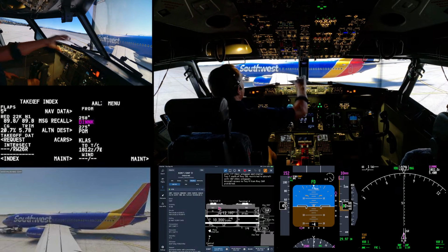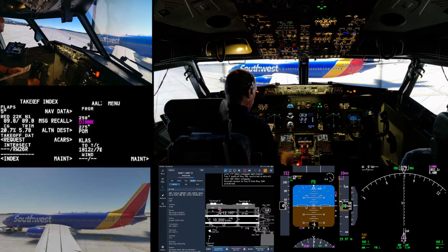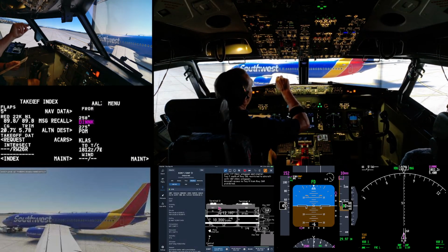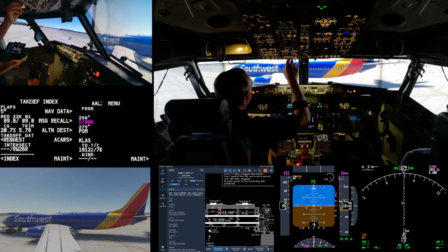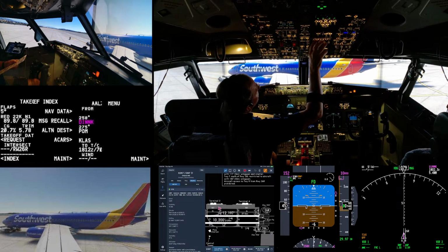All right, so we've got 2 good engine starts. Let's go finish the checklist here. Before taxi engine cutoff levers. Leave the parking brake set. So generator switches are on. 1 and 2 are on the bus. And electrical, hydraulics, engine hydraulics are all on. Window heat probes are on.